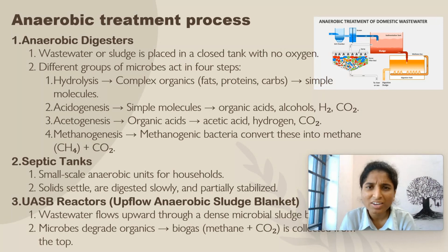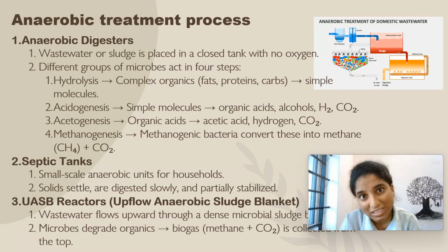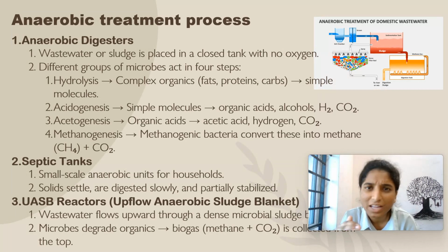Next comes the septic tanks. Septic tanks are not involved in STPs, but they can be used in smaller quantities at home, as household tanks, which are small scale anaerobic units for household use. And here the solids will settle, and these are digested slowly by the anaerobic bacteria, but they are only partially stabilized.